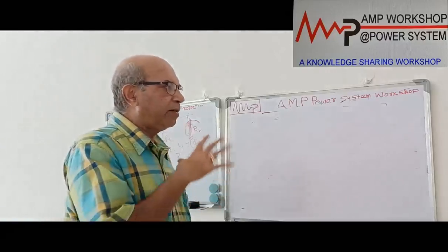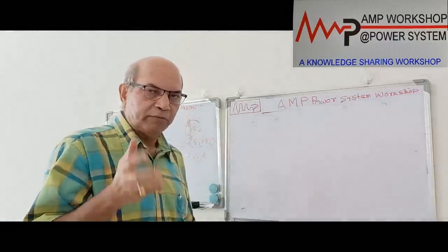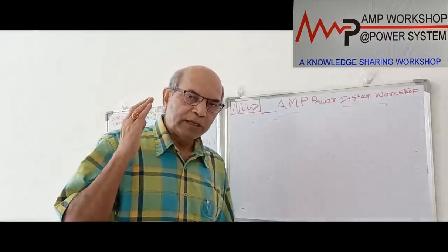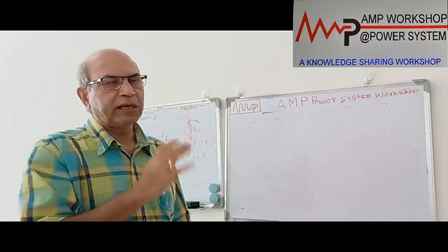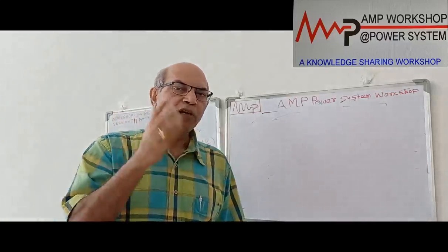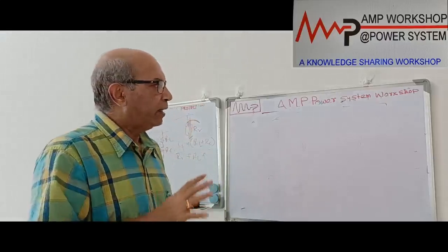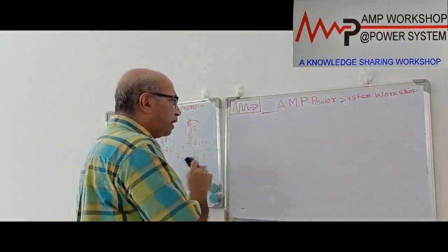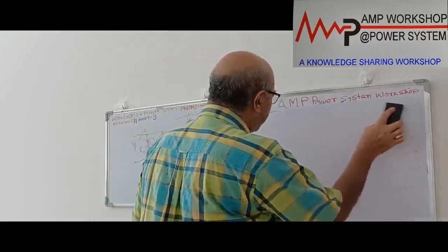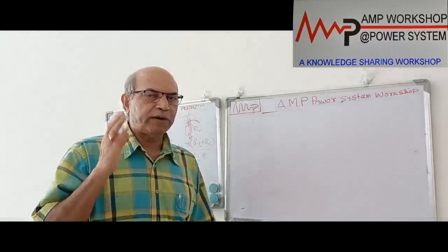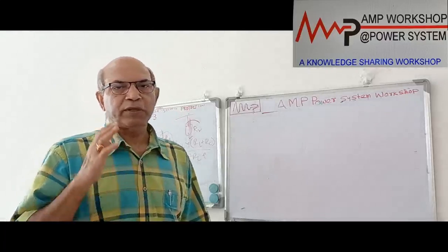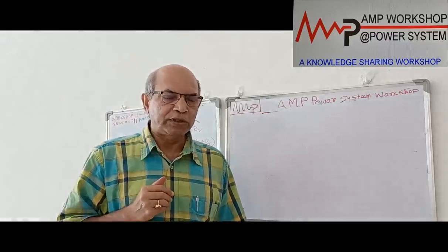And that is the best relay, because it is not susceptible to harmonics, not susceptible to the DC component, and not susceptible to CT saturation, because it is working on the voltage setting, not the current setting. Okay. Now we will discuss a couple more points on this when we are using any of the differential schemes. On the first day we said differential scheme is for the critical and high voltage switchgear.